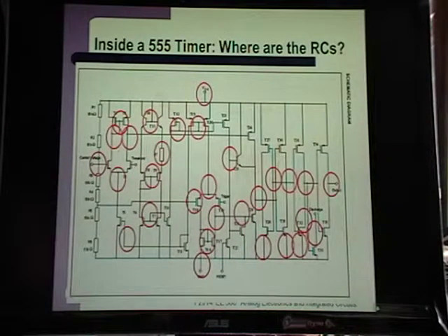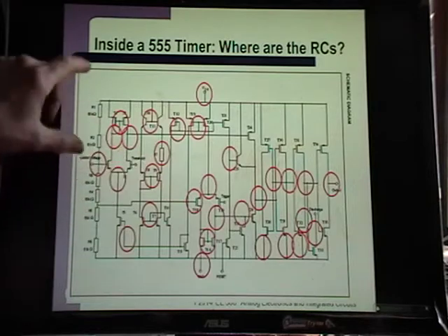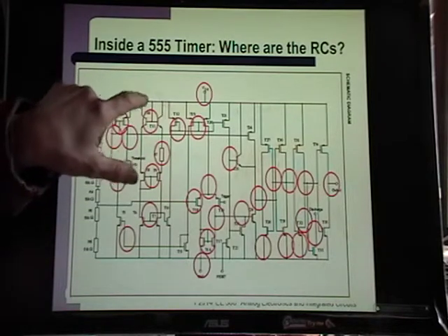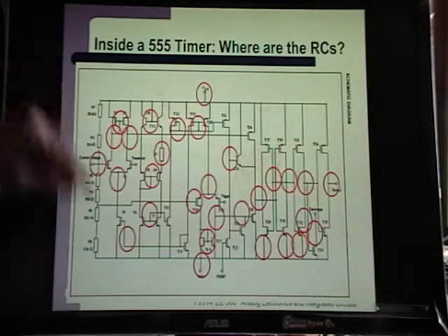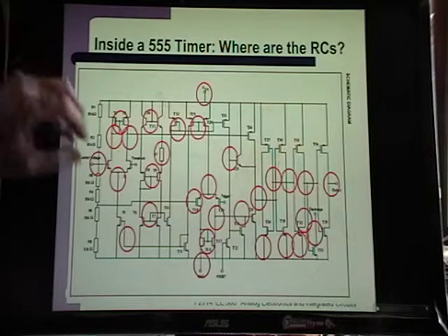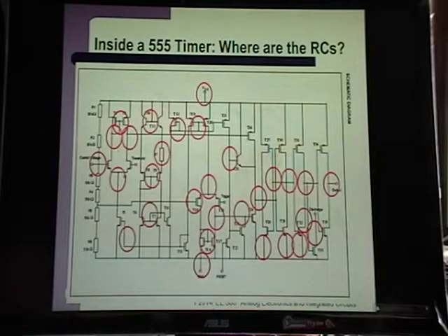And this is a 555 timer. But yeah, you follow the signal path. If there's capacitance on a supply, that's great because it quiets the supply. That's not a problem. But if it's in the signal path where you're trying to get something to move and it's changing the amplitude of that signal, then you have to pay attention to it.